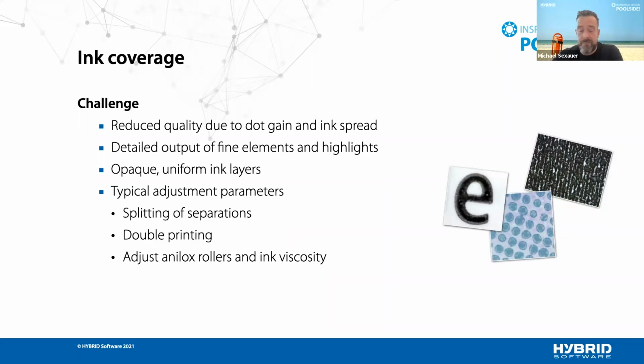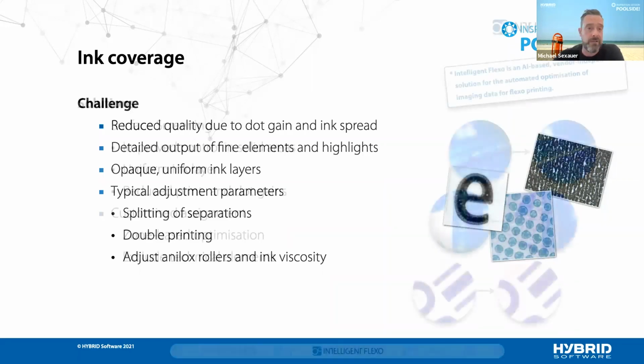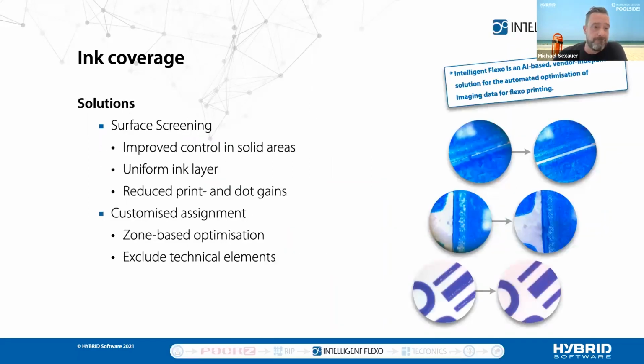Yes, of course. We have a really award-winning product that's brand new. Increasing the pressure of a solid area quickly causes significant ink spread. That's what we know. Negative elements get filled up and positive printing details can gain in thickness. In the end, barcodes are no longer readable, and so on. So solid areas suffer: the ink layer is not uniform and appears uneven and cloudy.